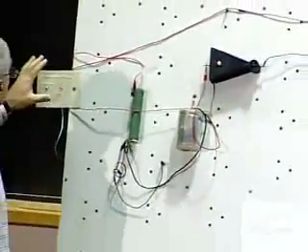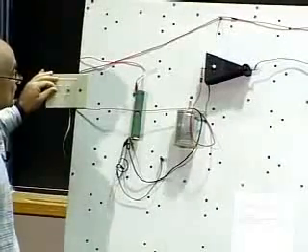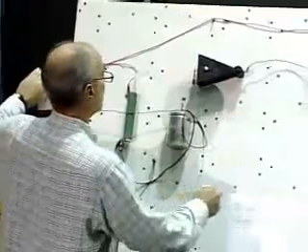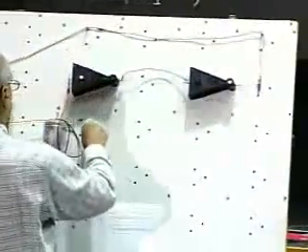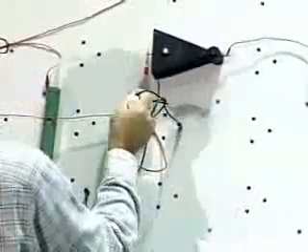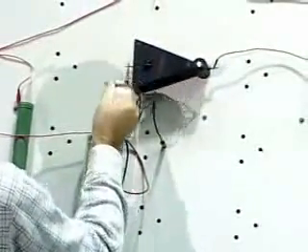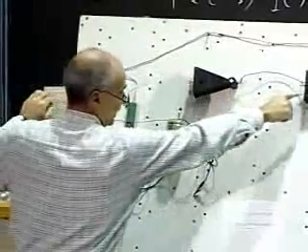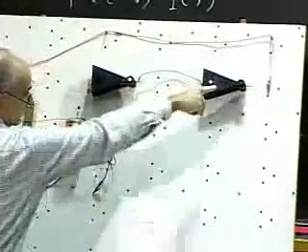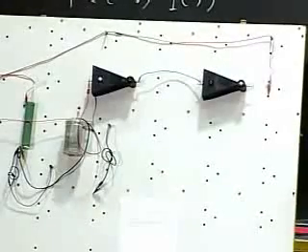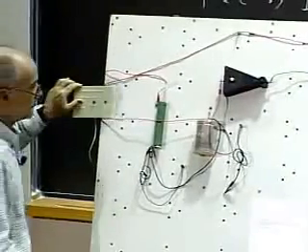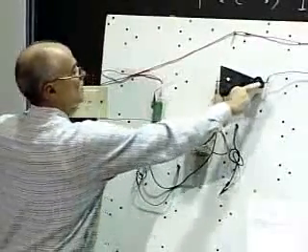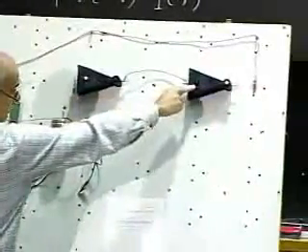Okay? So right now I'm charging the capacitor. In fact, let's see. Maybe I can discharge the capacitor first. Okay, so here the capacitor is discharged. As you can see, the input is 0, the output is a 1, and then the output of this inverter here is a 1. I have 2 inverters in series. Now I'm going to charge the capacitor. Okay, so I charged it to 5 volts. Okay, this lit up. This is off, of course. That's an inverter. This is a valid 0, produce a valid 1.